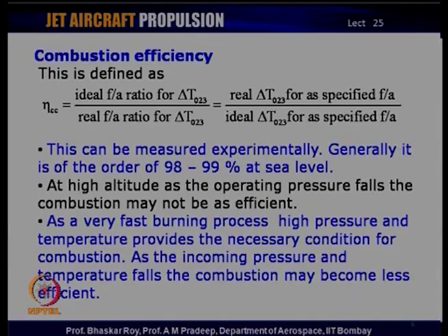When we are talking about combustion efficiency, we are talking about the efficiency with which the combustion process, that means the heat release process, is indeed carried out. The combustion efficiency can be defined in two different ways really. One, in terms of the fuel air ratio for a given temperature rise across the combustion chamber, or we can write the total temperature rise across the combustion chamber for a given fuel air ratio.